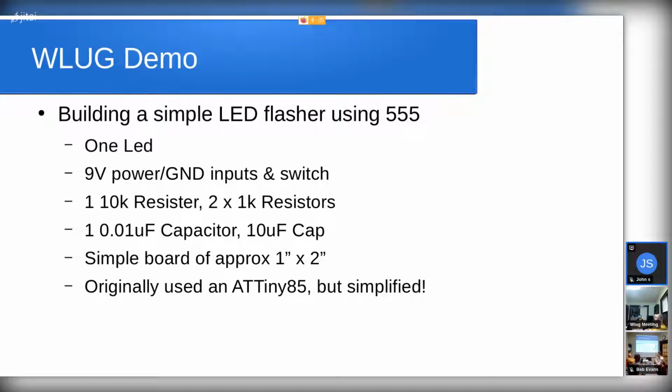But I wasn't doing any of the math to check the resistance and capacitance numbers to update it. I think the timing changes because that's RC. The voltage doesn't play, but the threshold moves down as the supply voltage moves down. If I dropped it to 5 volts, it could blink twice as fast. Can you simulate?